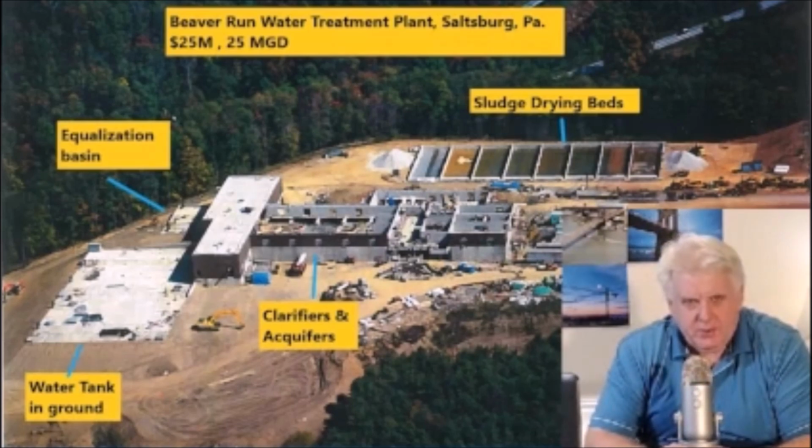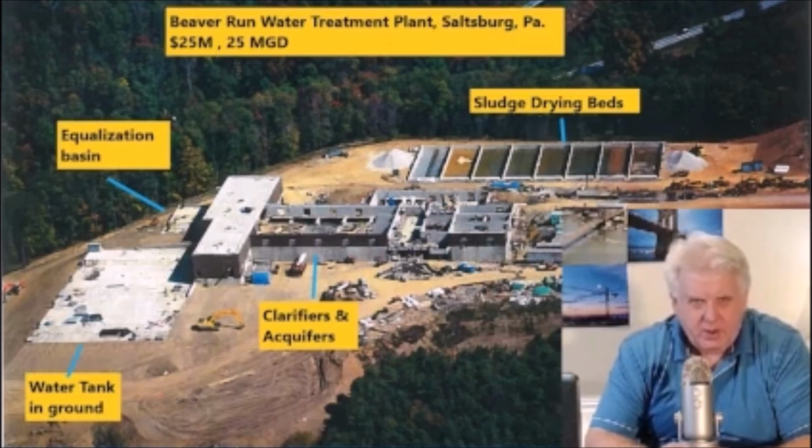And so we built the structure freestanding as the specifications and drawings called for, and we filled the tank with water, and we waited about 30 days. We had a small leak on the south side of the structure, and we patched it with some high-strength grout, and we waited another 30 days. We didn't have any problems after that.